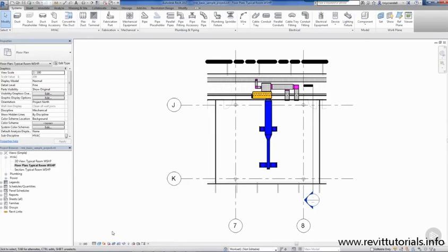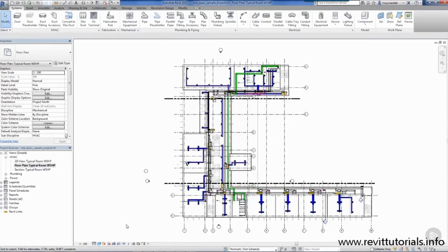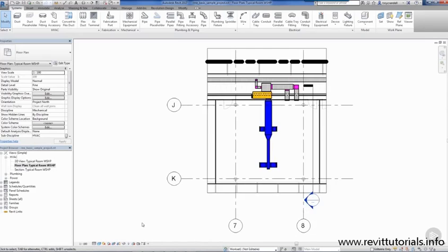The crop region defines the boundaries of the view. Cropping the view allows you to create views which focus in on specific areas of your design. Now, remember, you're viewing the same elements in all views, so to focus in on different areas, you basically create new views and adjust the crop as needed. The visibility of the crop is controlled here.